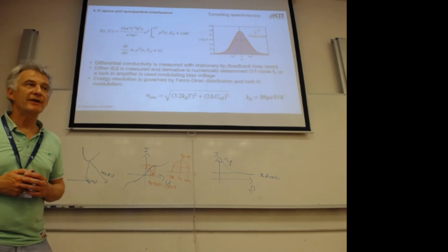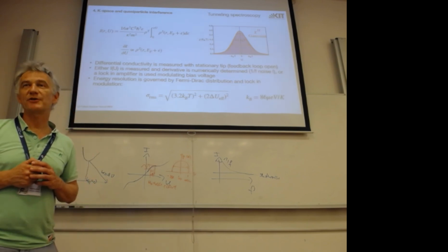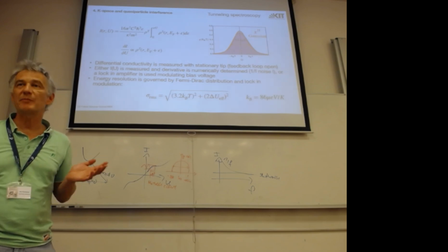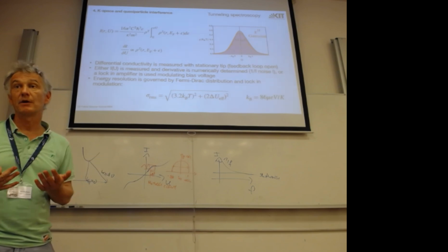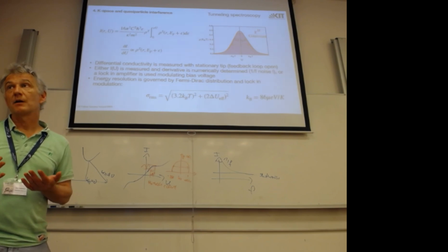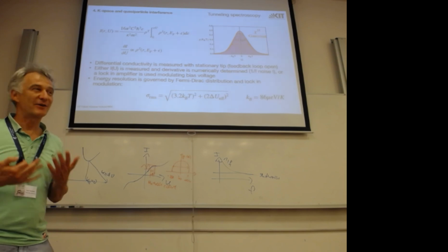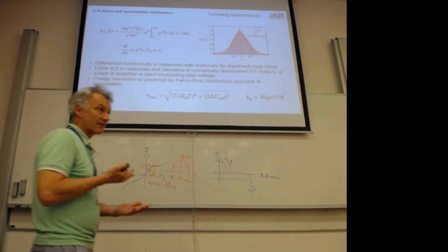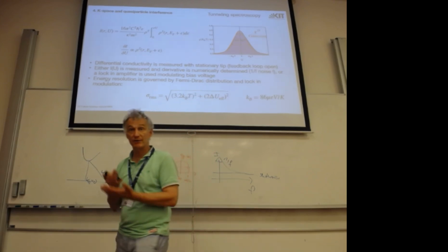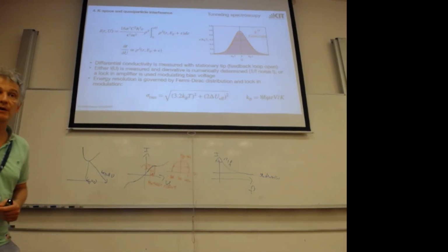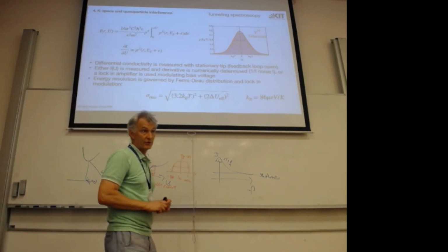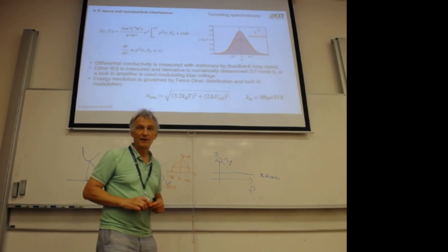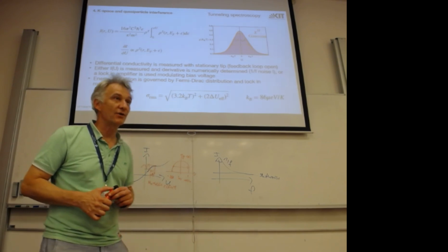So in the beginning of STM, these were IV converters with bandwidths of a kilohertz. Now we have IV converters with 100 kilohertz of bandwidth, so we like to go to a higher frequency, which I should warn the experimentalists here is there's also a capacitance. Tip and sample are a capacitor, so you get also capacitance charging. But the nice thing is this current is 90 degrees phase shifted to our tunneling current. Yeah, the tunneling current depends on U, and the charging current depends on U dot.